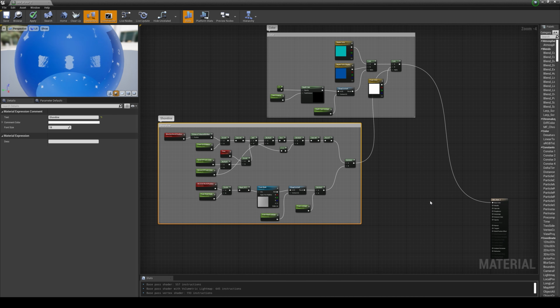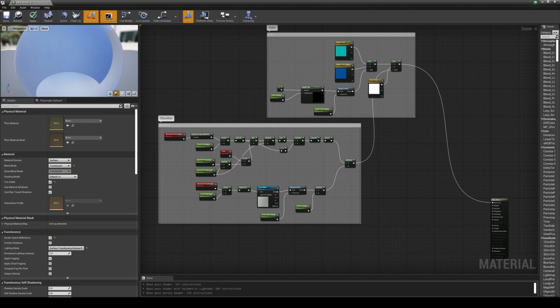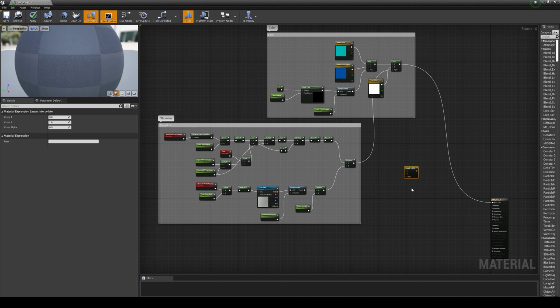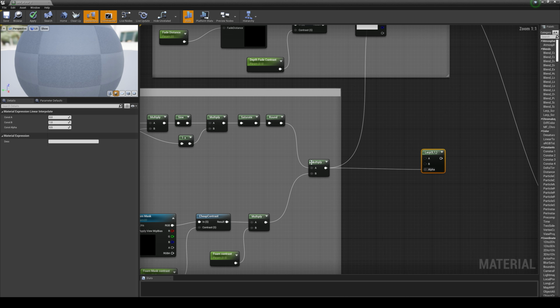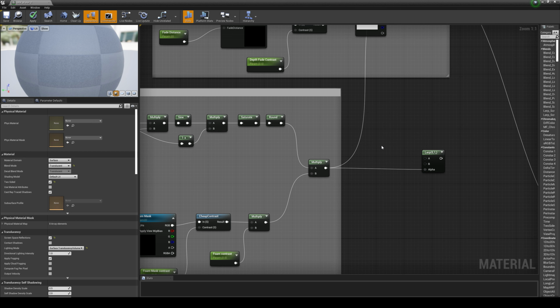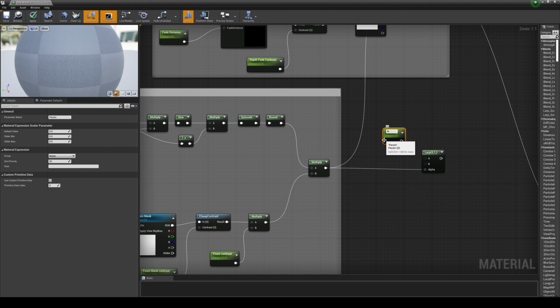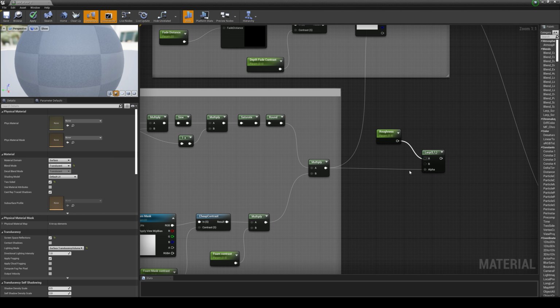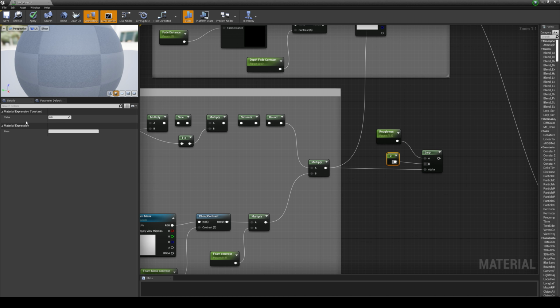So, and now we need to create specular, roughness, opacity, and refraction parts, and also normal parts. And let's start from the roughness specular. First of all, let's create a lerp node, L, and click on empty space, and plug in this part like this here. Let's create a parameter node, S and click on empty space and name it roughness. And change this parameter to 0.9.